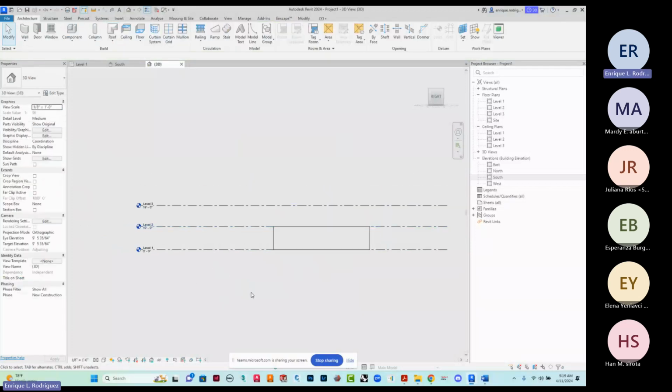Now, in the construction for this house, we're doing what's called platform framing, which means that we do the walls for the main level going up, and then we do the rafters going across to the outside of the wall. They will be resting on the actual studs for the main level. Well, that structure, the composite for that floor, is going to have about 1 foot in this case. Northern Home, we only had 10 inches because we were using 2x10s. We're going to assume here that we're using 2x12s plus a subfloor, etc.